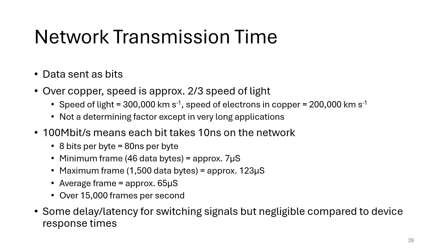And this is what I mean about latency. Each device that switches the message takes a certain amount of time to send that message. You've either got to handle the message within your Ethernet device, or you've got to switch the signals in the switch. But now that's beginning to add up, and that latency can cause a problem in some very high speed networks. Not normally a problem for PLC networks, we're running in the milliseconds.